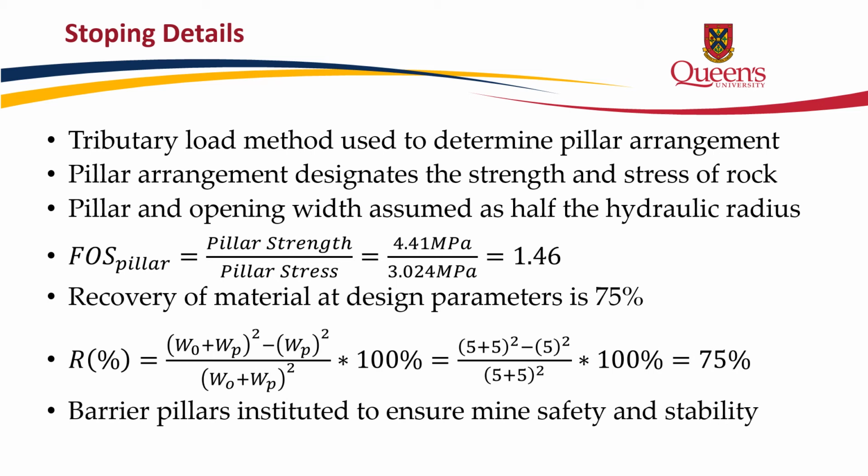Based on the pillar width and openings, the recovery can be found as 75%. Given the factor of safety, the barrier pillars will be instituted to ensure mine safety and stability over time.